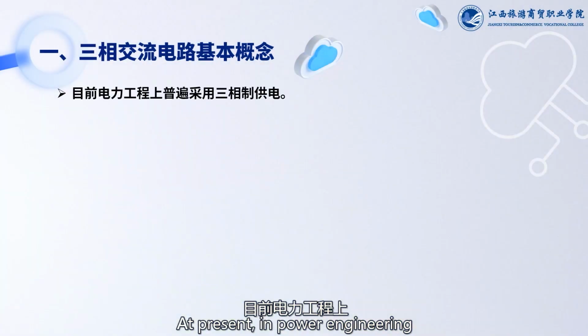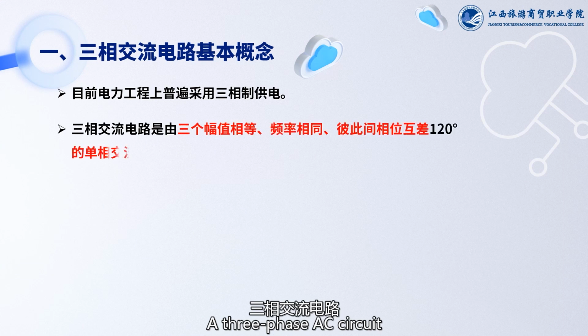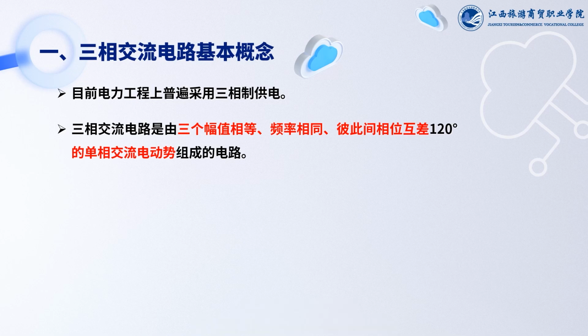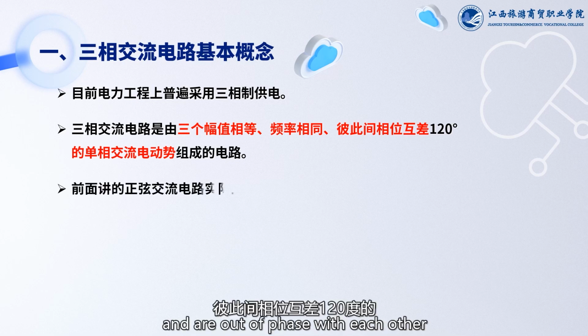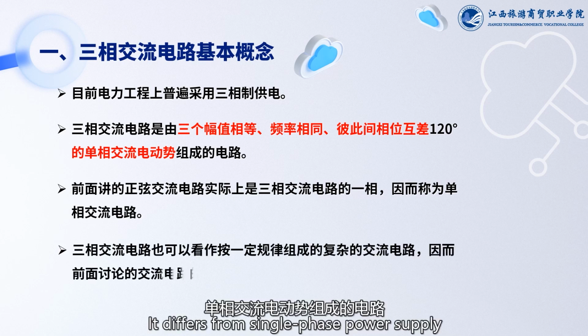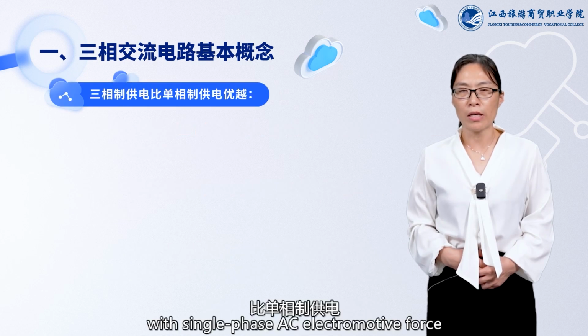At present, in power engineering, three-phase power supply is widely adopted. A three-phase AC circuit consists of three sources that are equal in amplitude, with the same frequency, and out of phase with each other by 120 degrees. It differs from single-phase power supply, which is composed of a circuit with single-phase AC electromotive force.